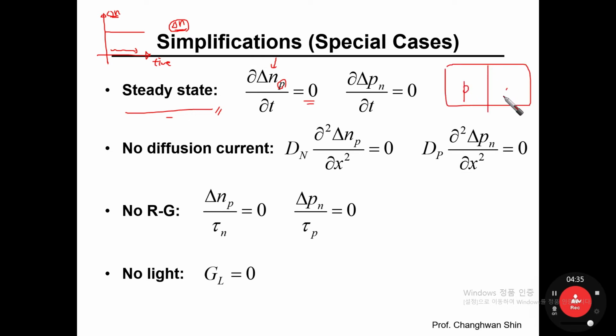In a p-n junction diode, positive bias has been applied and electrons are now injected into the p-type material. This injected electron in the p-type material would significantly affect the minority carrier n sub p, right?